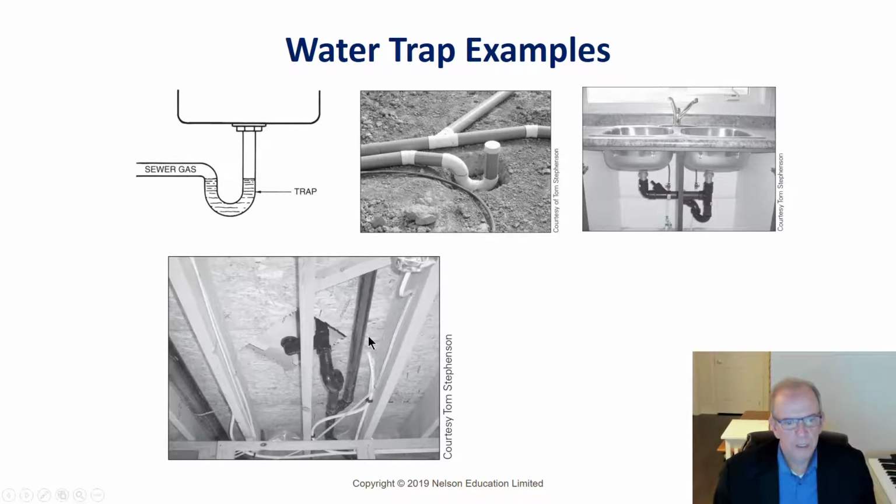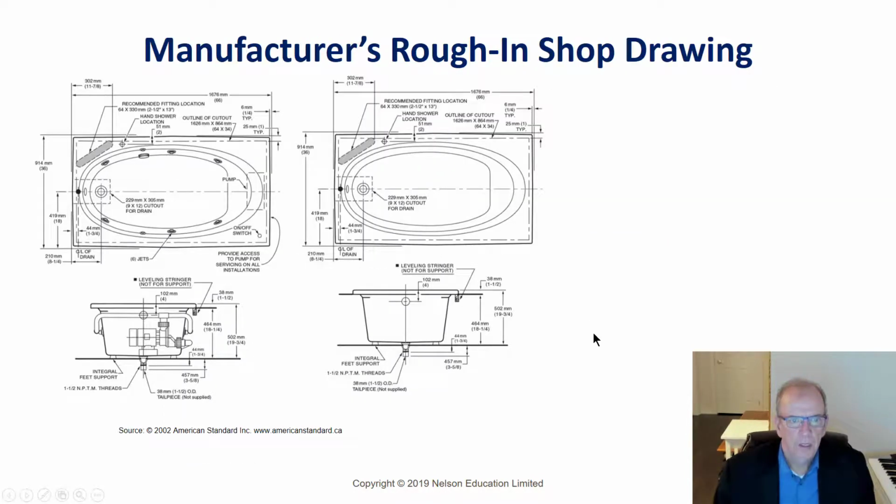And then this pipe over here is your vent pipe coming off of your drain. So you got the trap, your vent going back to probably a wall that'll go vertically up. And here you got your floor drain listed, and there you got your P-trap for your sink, double sink, and this goes back in the wall and down. You can't see that. And then this will be connected with a pipe from the dishwasher, the discharge water from the dishwasher.